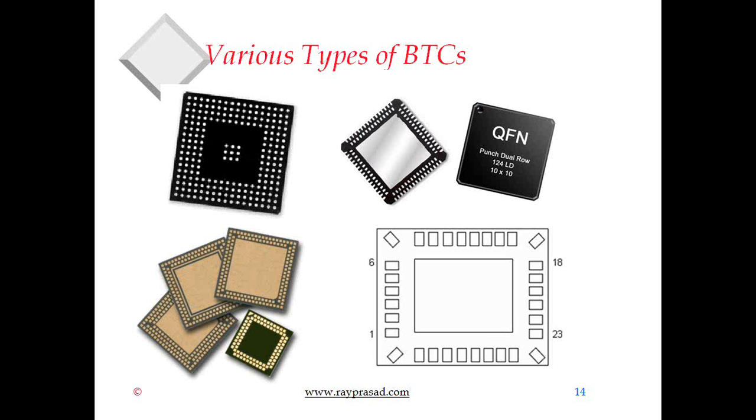So essentially, when you're doing a design, you have to look at the data sheet before you do a board design, because you have to match that footprint, as opposed to QFP or PLCC or some other kinds of packages that we have.